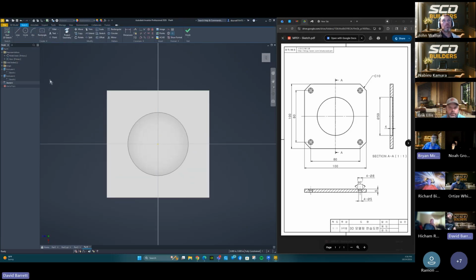Go ahead. I'm sorry, I got a quick question. Whenever I click on my circle, or whenever I click on the left side of the little properties thing and I click on extrude, it doesn't pull up a menu. I'm not sure why. You have multiple screens, multiple monitors. Your little property tab might have transferred over to one of your other monitors. It's hiding. Okay, I feel like a dumbass.